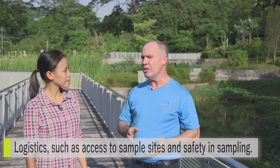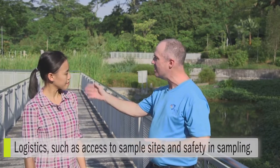And these logistical issues include things like how easy is it to get access to the water to collect a sample. Now, there are a number of different design methods that we can use to collect samples, so let's talk about some of these to begin with. One example of a design method is purposive sampling. With purposive sampling, what we're trying to do is identify sample locations with a specific purpose.